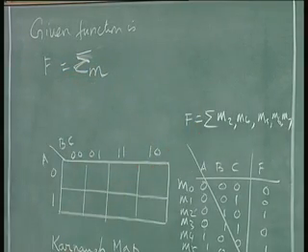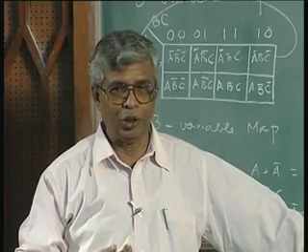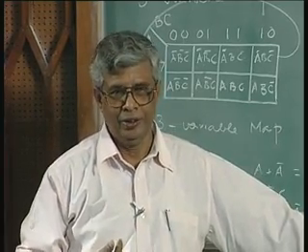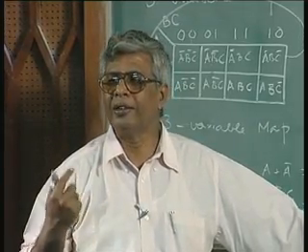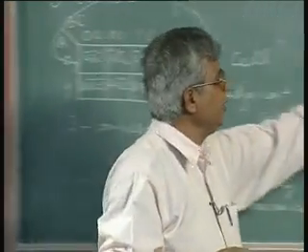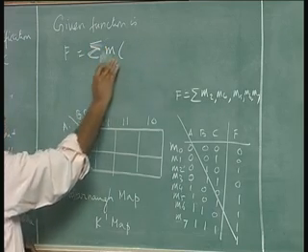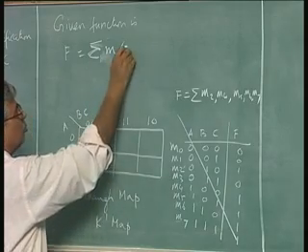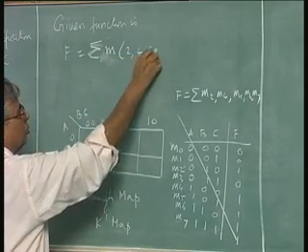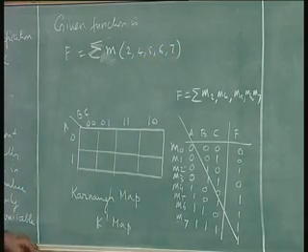See, we try to minimize having to repeatedly do the same thing over and over again, out of laziness or whatever you want to call it, or you want to save stationery, or it is just monotonous, boring. So, all you have to say is sigma m means the sum of products, and what are the product terms involved? Are the minterms 2, 4, 5, 6, 7. So, if I give you the function like this, f is equal to sigma m 2, 4, 5, 6, 7,